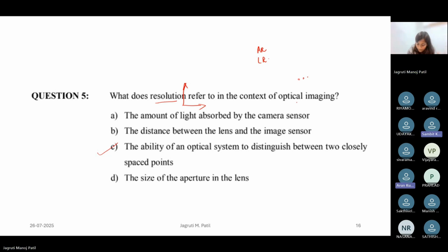Aperture size also does matter, right? Yeah, exactly. The aperture size will matter for resolution, and where you're trying to focus will also matter, because if that particular plane is not at the natural focus of your aperture, then the object might get blurred. So where you're focusing, where you're not focusing, and the number of elements that you have in that particular aperture, all will affect the resolution of the system and eventually the resolution of the image that you get.